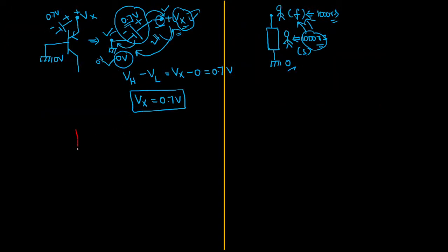Now, let me draw the second diode. Let us keep our attention on the second transistor. Now, I am focusing at this point. Across this we have one more source, not source, diode cut-in voltage, and this is the base terminal. This terminal is having 0.7 voltage. How can we redraw this circuit? So let me draw like this. So here I am having 0.7 voltage, and from this I am just starting.